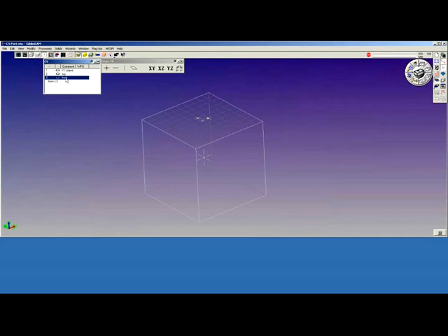I want this on the front of my cube. And as you know, the coordinate system that was created is a duplicate of the top coordinate system. So I'm going to change the planar orientation by making it an XZ coordinate system. It stands it up vertically, giving me my ZX orientation, X positive to the right, Z positive upwards.